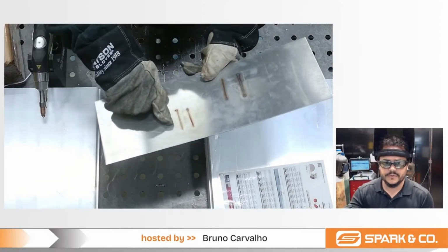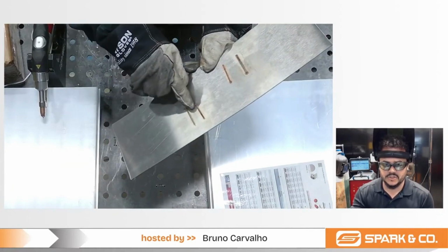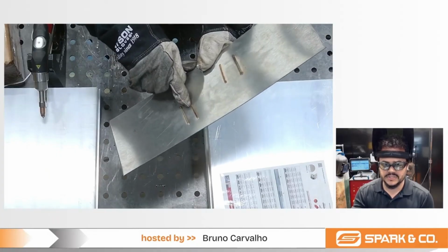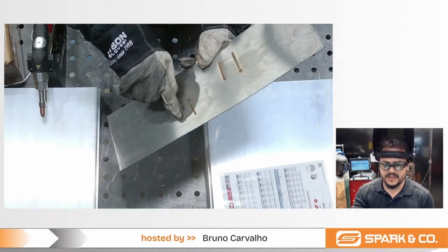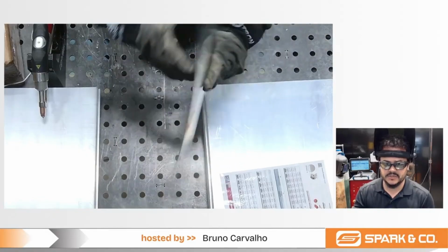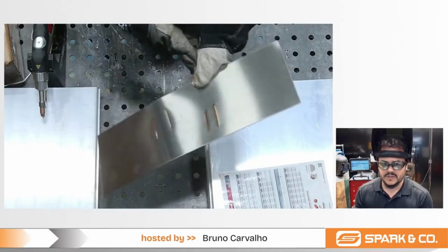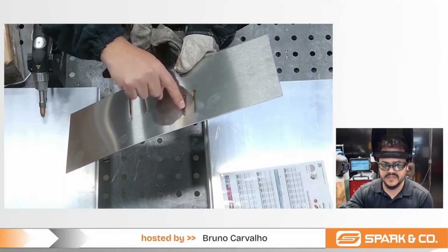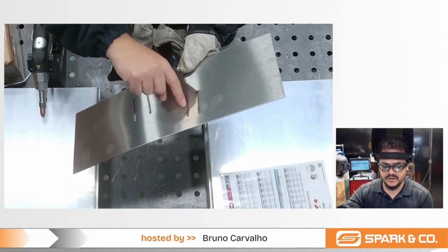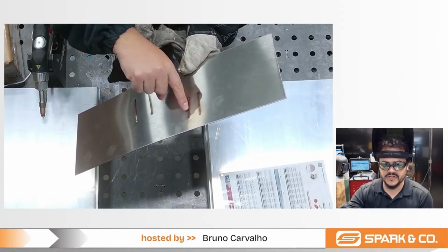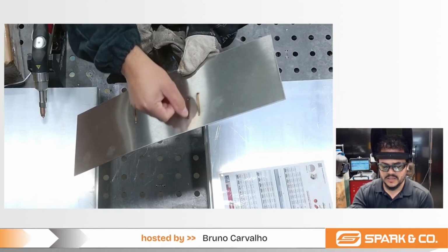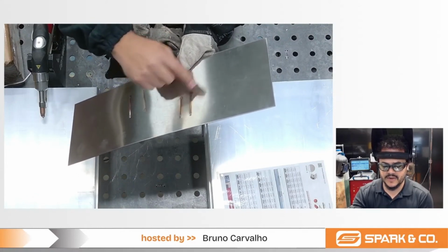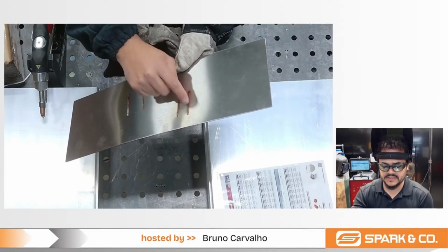So here we go. On this side, I did 2 beads, right? First one, no compensation. You can even see a little bit more discoloration on this one, and this one here, less discoloration. When we look at the other side, I don't know if you can tell on my camera, but on the sides I have the same issue that I showed you in the picture. On the sides here on the welding toe, the penetration is too much, so the laser is burning through, and here it's flush, so I know the laser is not passing through. This is what we want.